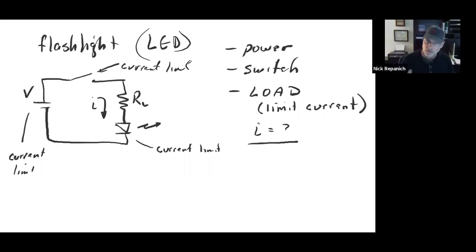And for some reason, a lot of people get this far along thinking, oh, it says 2.6 amps, that means 2.6 amps is going to come out of it. No, that means it can supply up to 2.6 amps. If you have a circuit that takes a third of an amp, you can run 1, 2, 3, 4, 5, 6, 7, 8 circuits on 2.6 amps, right? And you'll be okay.